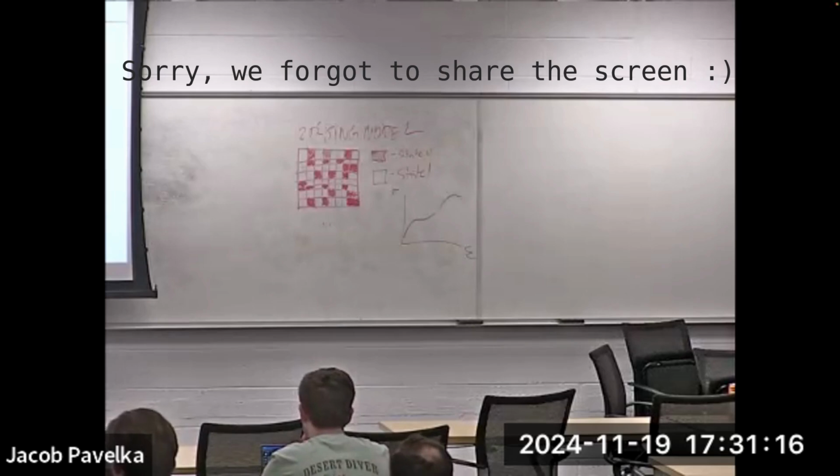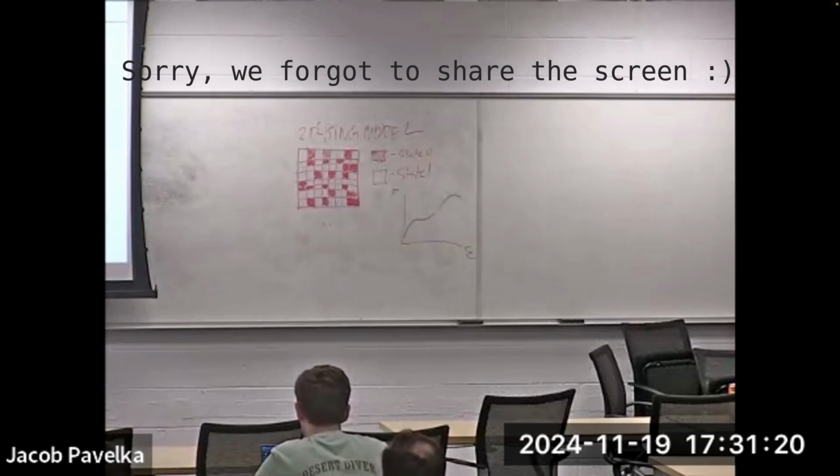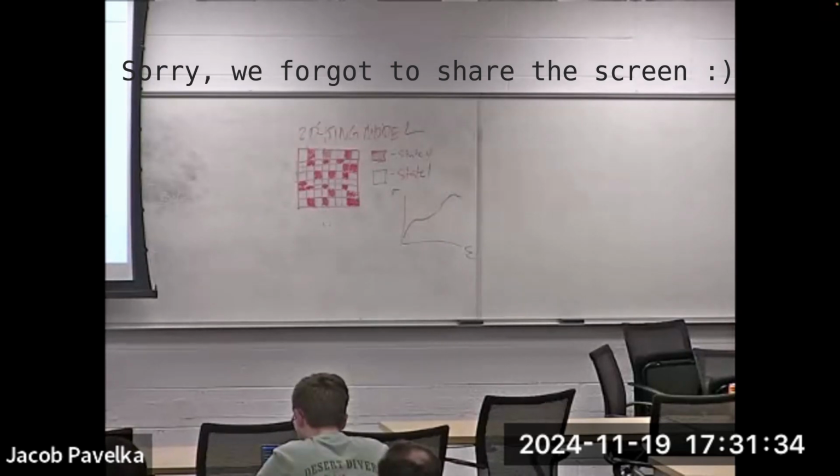The PRM file defines many things. First, what is the order of your finite element? What's your order of quadrature? These things typically never change, so just leave them. Number of dimensions: we are going to do 3D all the time probably. And here's the size of the domain in different directions. So I think Chaitali's recommendation is that I make the X bigger.